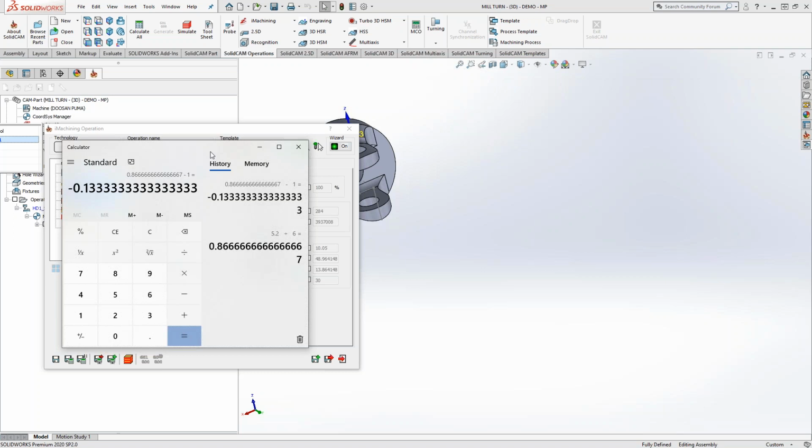So I would go back to my iMachining definition for that material in the machinability factor section and type in minus 14. Minus 14 machinability factor. Now I'm dialing it in even further for that material. Does that make sense for everybody? Makes sense to me. Because again, we're trying to optimize this. So not everything's going to be able to be captured by just a quick data entry like that. Some of this will have to be tested, basically.